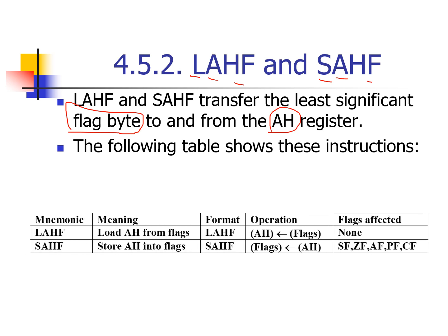And these are the instructions which are used to do this. LAHF takes the flags into AH. The flag bits are stored in AH with load F into AH. SAHF, store AH into F, takes whatever value is inside AH and stores it in the flags.